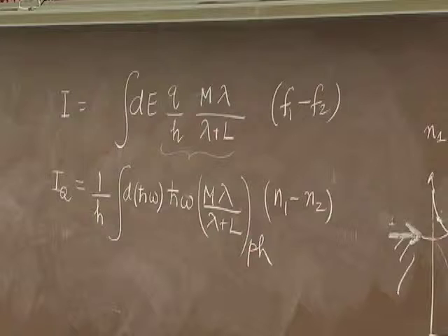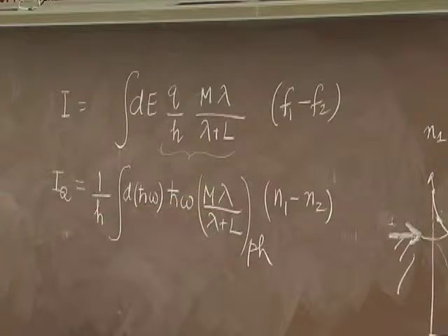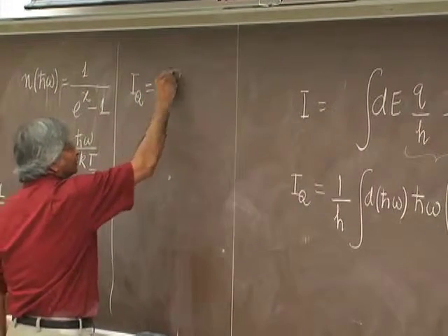So lambda here is the phonon mean free path. However phonons are getting scattered, and often those mean free paths depend on boundary scattering and all kinds of things. You would have to understand a lot about the phonon system to know what to use there. Now for this one, again you could do this linearization, so you could try to get an expression for the thermal conductivity. So G.